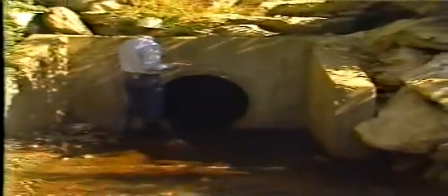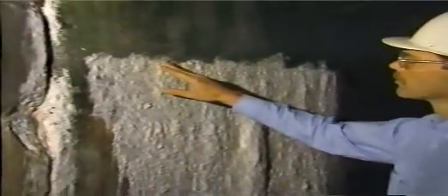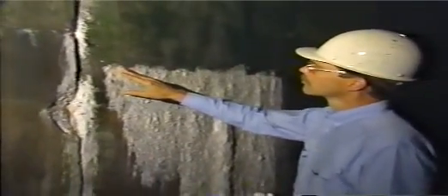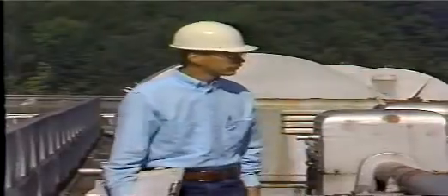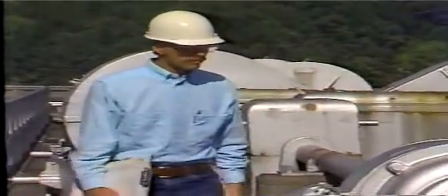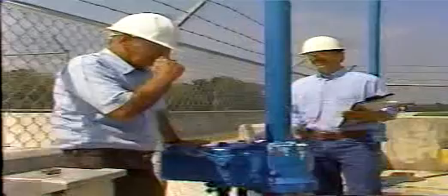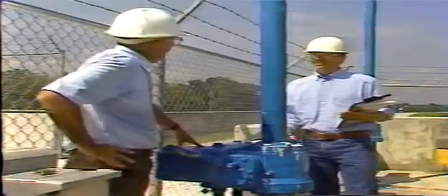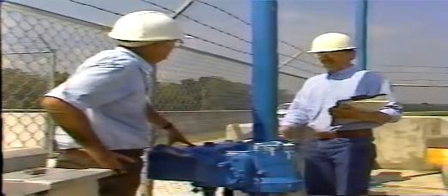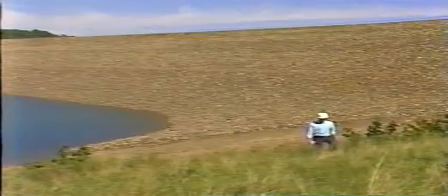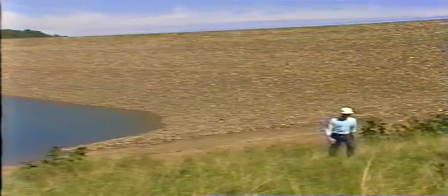This presentation covered deficiencies you may encounter as you go about your duties at a dam. Take time to be observant about the condition of all features of the dam. Your observations are important. Remember, be alert to anything unusual and always look for any changes that may have occurred. Report any concerns to a facility engineer or the appropriate authorities. Your efforts will help ensure the safety of the dam.